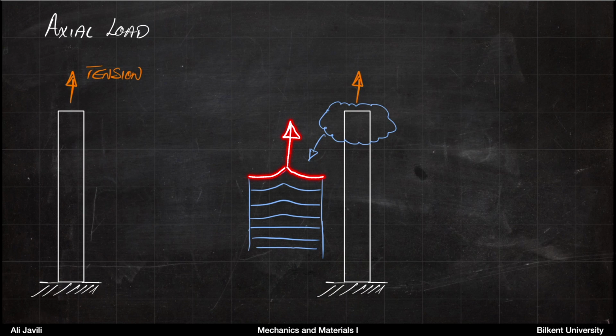So if you think of a cross section on top of that bar, you can clearly distinguish between the point at which you apply the force and the edges. If you go further down a little, you see less dominant effect from the location of the force, and the further down you go, you see less and less of that local influence of the force.